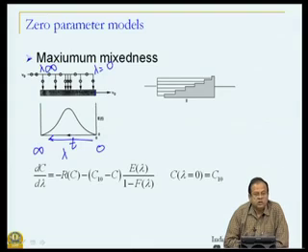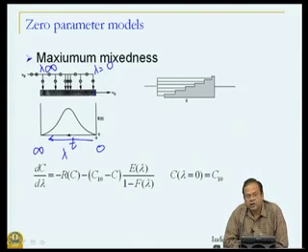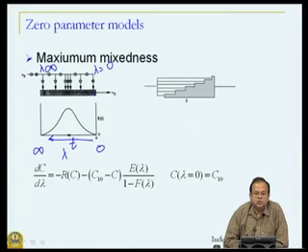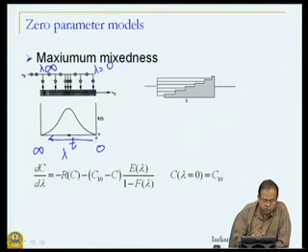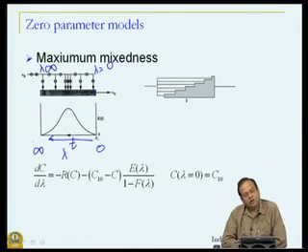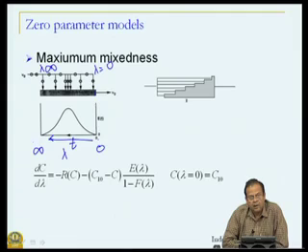The fluid element which enters the earliest leaves the last. The fluid element which enters last, at the exit point, leaves earliest. So, my exit age distribution is now from t equal to 0 over here to t equal to very large values. And what happens in a plug flow reactor?